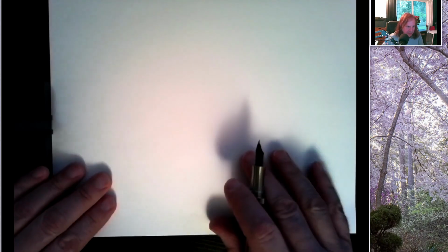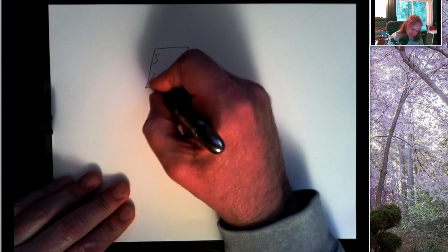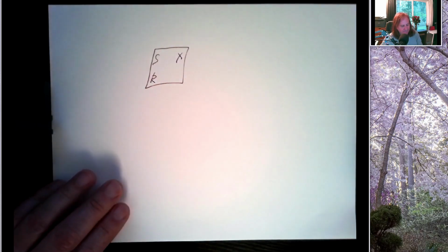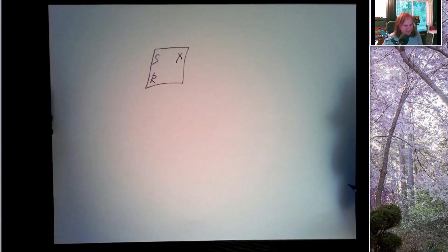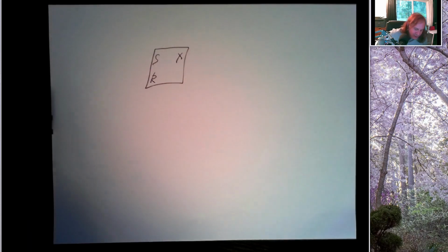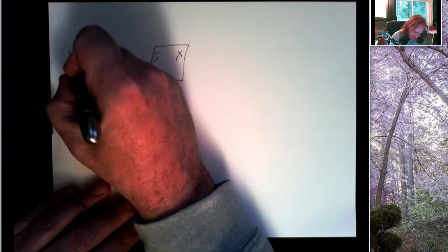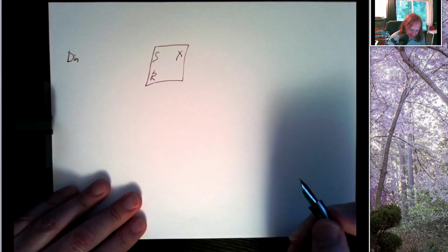All right, so let's make a few more embellishments to this design. We have our basic set reset latch. But it would be more useful to have a device that we can simply feed a bit into and say, remember this bit, and it'll ignore that input until we say remember this bit, and then it'll remember it. And we can do that with a little bit of external circuitry. So I'm going to have a data input signal, and I'm going to have a load signal.